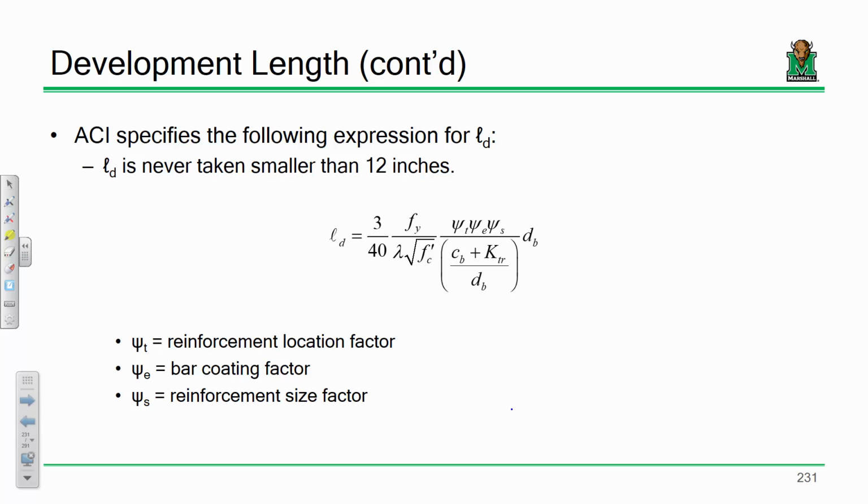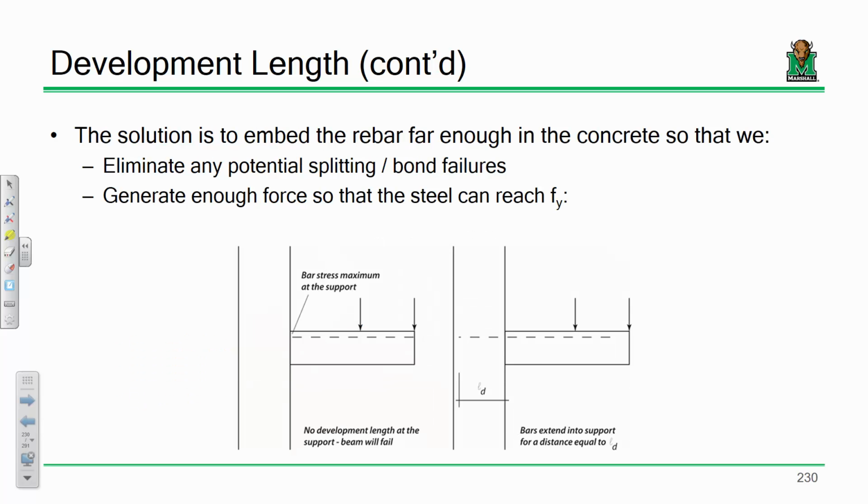Okay. So the rebar development length is how far from the end of... Yes, yes. So for instance, in this situation, the development length would be how far I would need to embed this particular bar in order to develop its full capacity. That's why we call it development length, so that we can develop the full capacity of the rebar. What were you going to say? Because you sort of said something too.